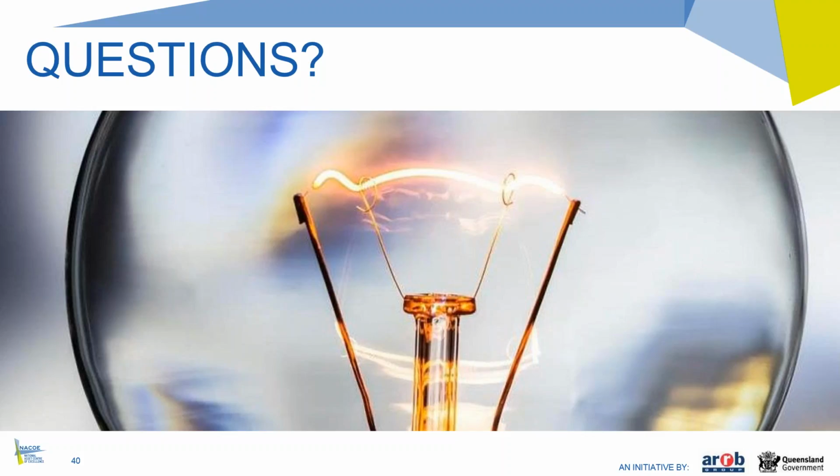Other than that's spot on, Angela. I was going to get to that a little bit. Thank you. And one part of that, and I'm just stealing my own thunder here, but one of the effects that wasn't very well understood before is that not just does it revert to sinusoidal loading, also the strain level is half. As a result of that, the actual effective strain level in the specimen is half of what you assume in the haversine test.